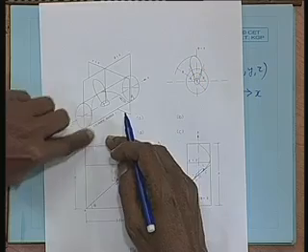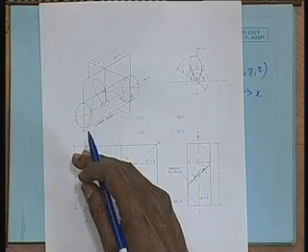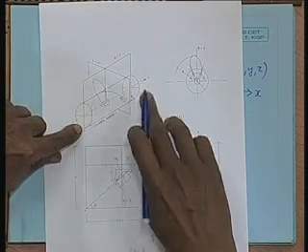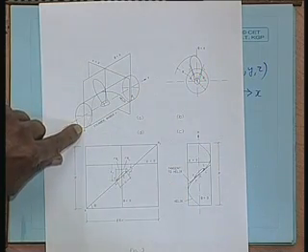So, if I open it up, it will open up to 2 pi r, right? And the distance here along this axis, if it has moved through a distance called pitch, right? I have not defined pitch earlier. That is, when this line moves through one revolution, the distance it has travelled longitudinally or axially is called the pitch of the helix or helicoidal surface, if the entire surface is moving the same distance.